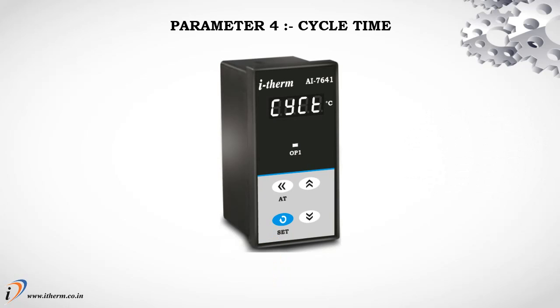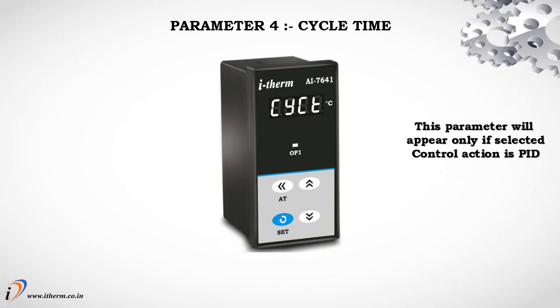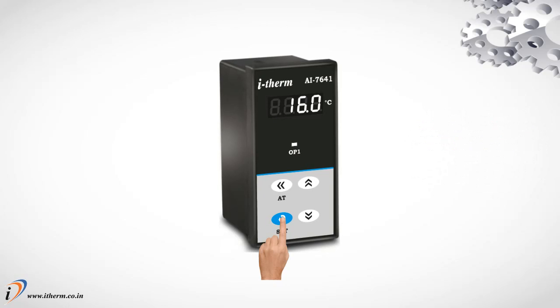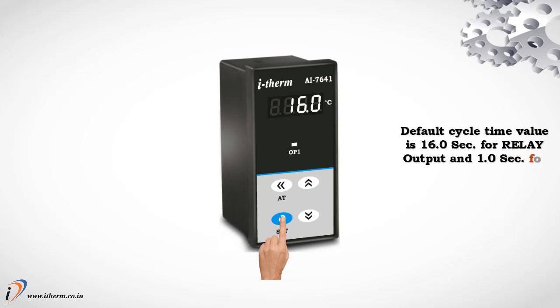Parameter 4, cycle time. This parameter will appear only if the selected control action is PID. Default cycle time value is 16.0 seconds for relay output and 1.0 second for SSR output.